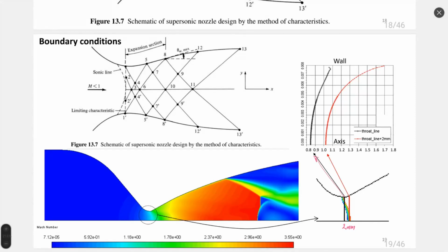In terms of performance, which approach would be the best? Method of characteristics or other approaches such as parabolic approximations or others that exist for rocket nozzles? Nice question. Parabolic approximation, as it follows from its name, is an approximation, a way to represent the solution of method of characteristics in some simple function, a parabolic function. So we use a parabola to explain a complex flow concept. From the point of view of time expenses, of course, parabolic approximation is easier and simple, right? Just use a spline or just one parabolic function and you already obtain the nozzle profile.